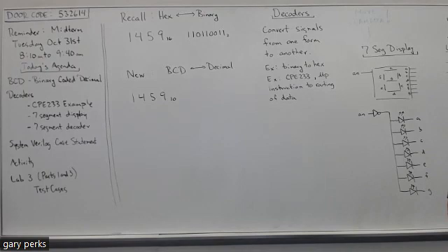Once you know what a decoder is, and I'll explain how you model a decoder in Verilog, you'll have the last piece you need to do Lab 3, which is taking those 3 modules and connecting them in a certain way where the entire circuit will add 2 binary numbers, 4-bit binary numbers A and B, with the RCA. But instead of displaying the result as binary on LEDs like you did in Lab 2, you'll display the result as a hex character on a 7-segment display. So one of the things we'll talk about is how the 7-segment displays work on your Basys board.